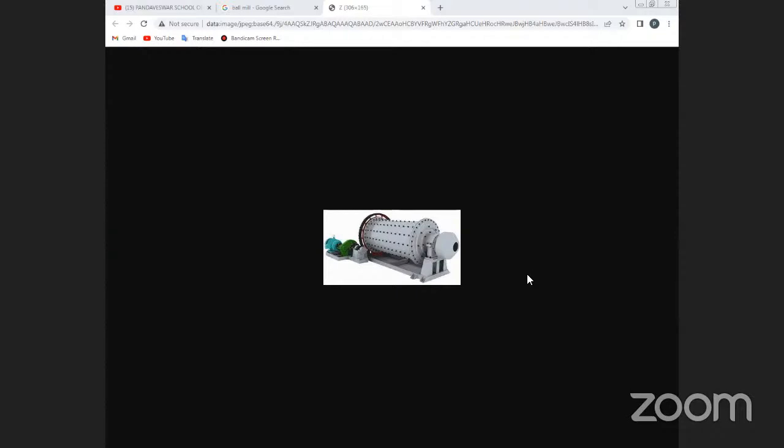The amount of material fed into the cylinder of the mill should neither be too large, as it may exert a cushioning effect, nor be very small, which may lead to loss of efficiency or abrasion. The cylinder is rotated on its axis with a rotational frequency of 0.5 per second. The speed is 0.5 per second.